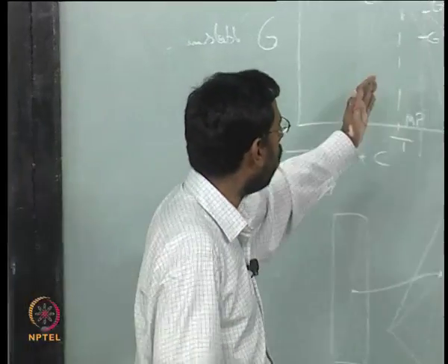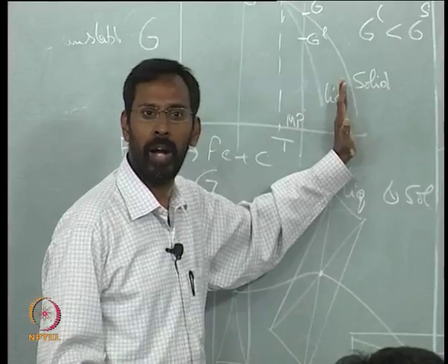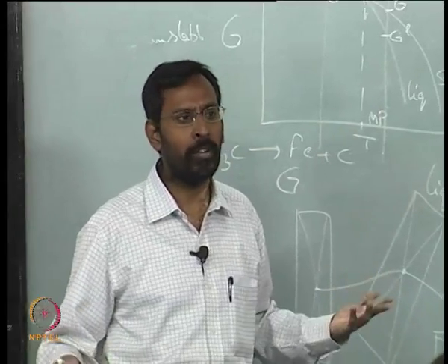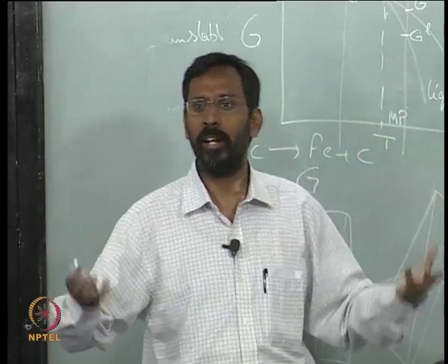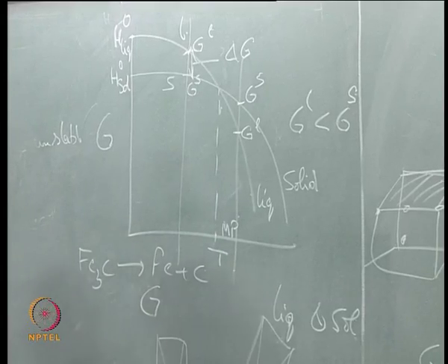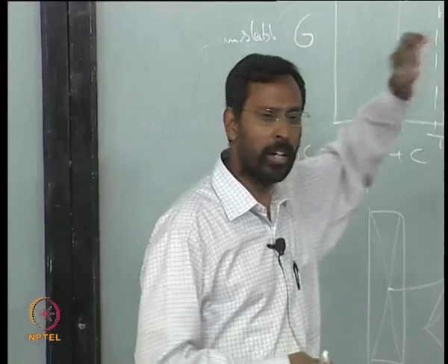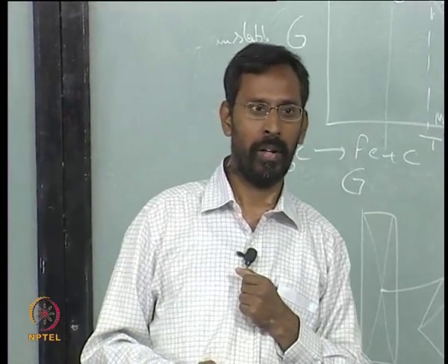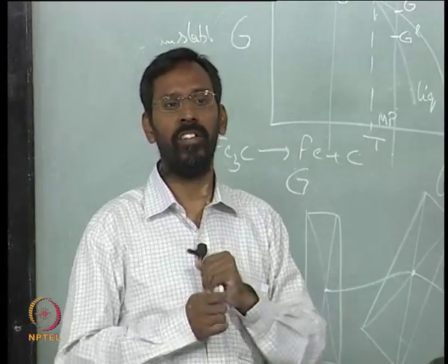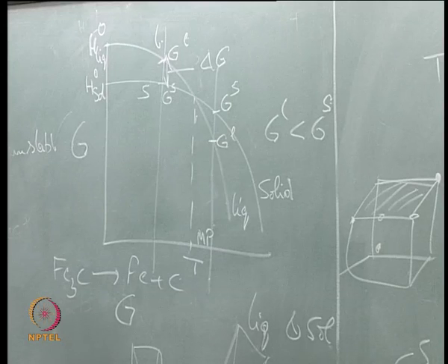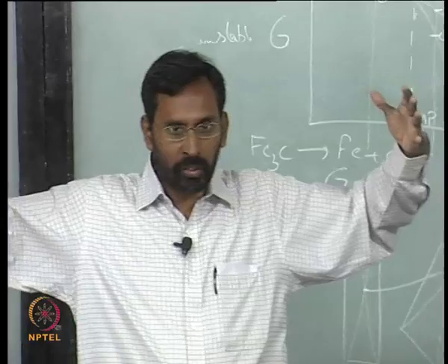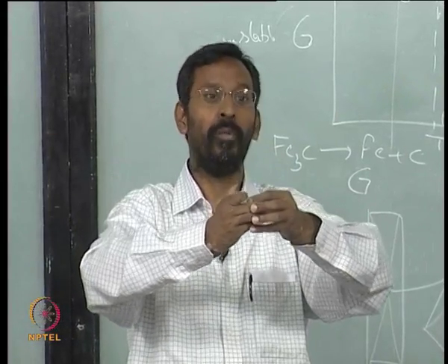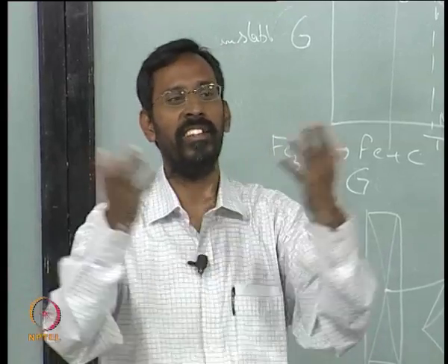Why? Because I am at a temperature above the melting point, I am at room temperature. I said at room temperatures the liquid is more stable than the solid. So ice cannot remain as ice, it wants to transform to a liquid. So that particular region which is the highest energy immediately transforms. Then the edges start becoming rounded, and then the surface, and so the actual melting starts from the surface and goes into the interior. Why? Because the surface area is available for it.